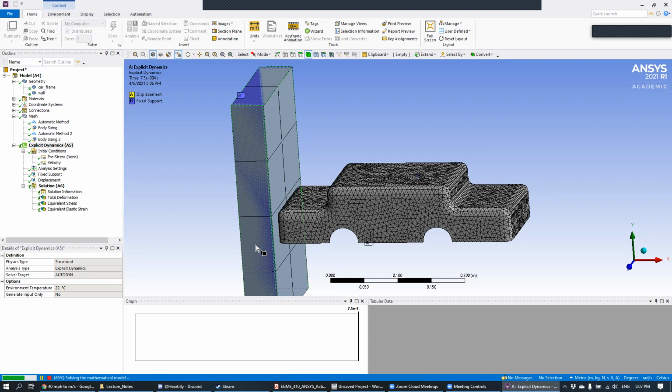I just made my mesh really coarse, and it's still not liking it. Okay, yeah. I'm not sure if they just prevent it entirely because it's a student version, but theoretically there's nothing stopping you from doing that, and there are a lot of applications that do use quadratic elements for dynamic simulations. I think it's just a feature that they hide for the academic version. That's what I'm guessing. Gotcha.